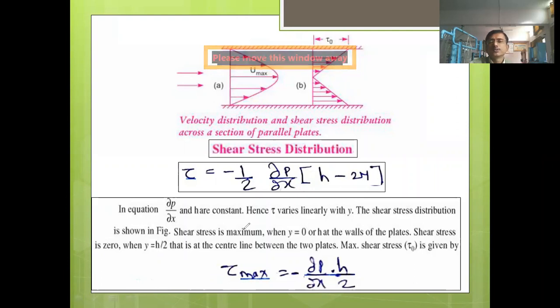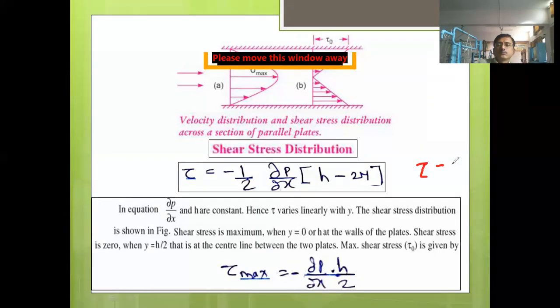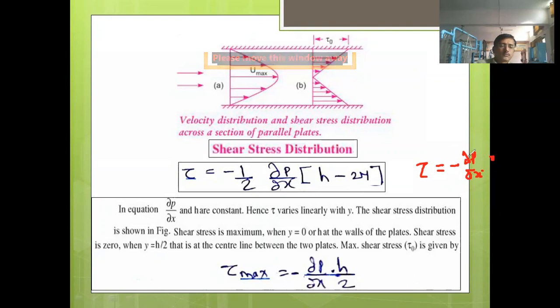Next comes the shear stress distribution. This is the formula for shear stress distribution. Tau is equal to minus 1 upon 2 del P upon del x into h minus 2y. What was the formula for the circular shear stress distribution? Does anyone remember? Tau is equal to minus del P upon del x into...